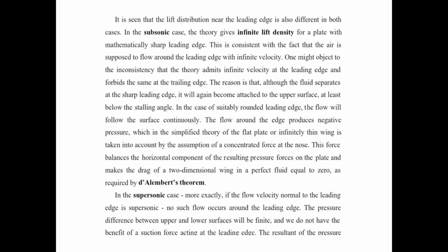It is seen that the lift distribution near the leading edge is also different in both cases. In the subsonic case, the theory gives infinite lift density for a plate with a mathematically sharp leading edge. This is consistent with the fact that the air is supposed to flow around the leading edge with infinite velocity.